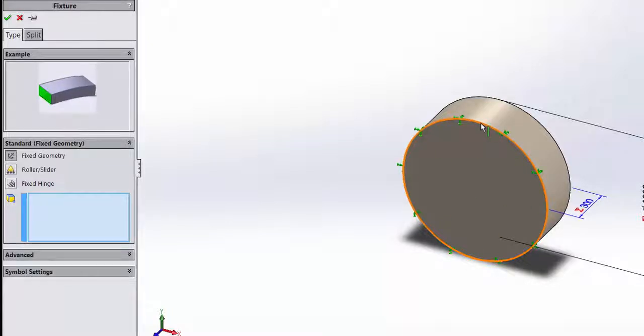For the purposes of this demonstration, we will fix the bottom edge such that none of these nodes that will exist once we create our mesh will be allowed to move. For your third project, you'll want to fix the entirety of the face of your beams.